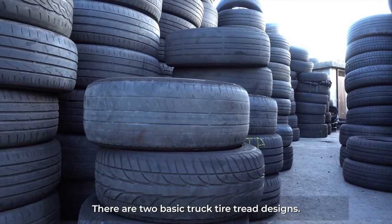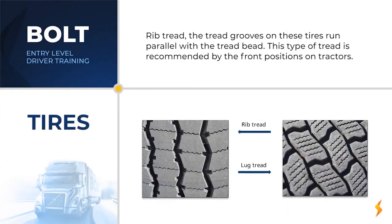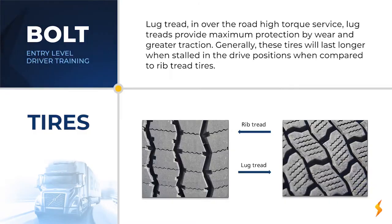There are 2 basic truck tire tread designs. Rib tread: the tread grooves on these tires run parallel with the tread bead. This type of tread is recommended for the front wheel positions on tractors. Lug tread: in over-the-road high-torque service, lug treads provide maximum protection from wear and greater traction. Generally, these tires will last longer when installed in the drive positions when compared to rib tread tires.